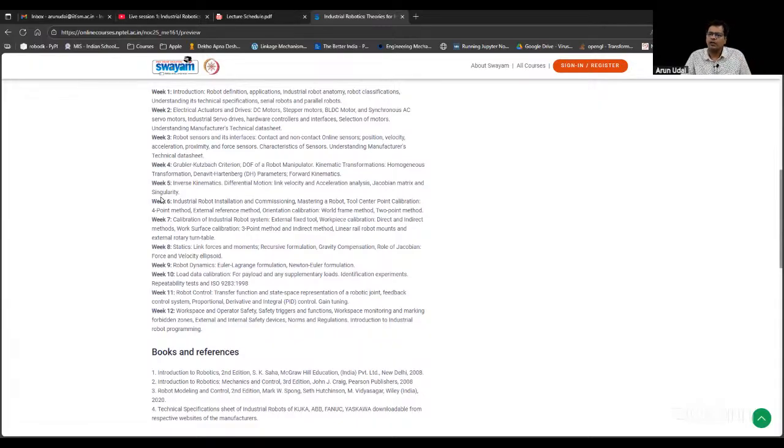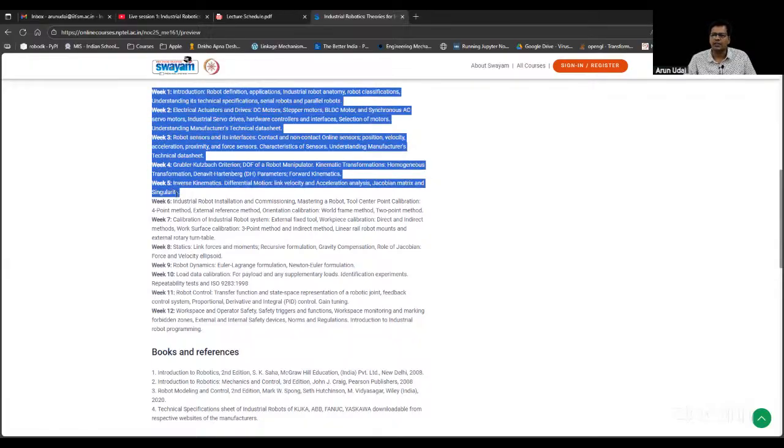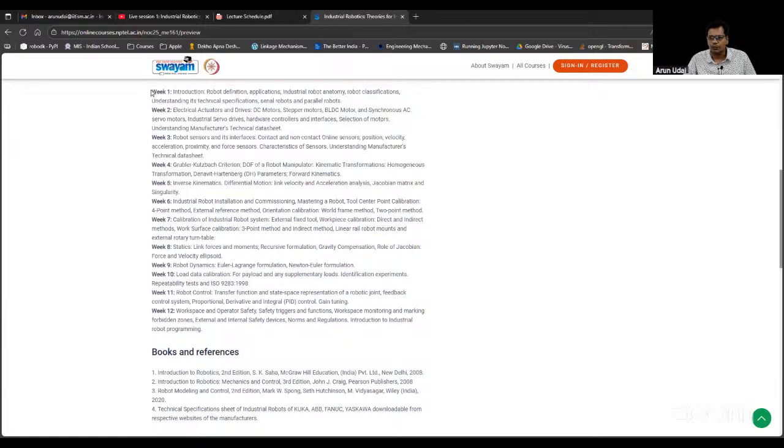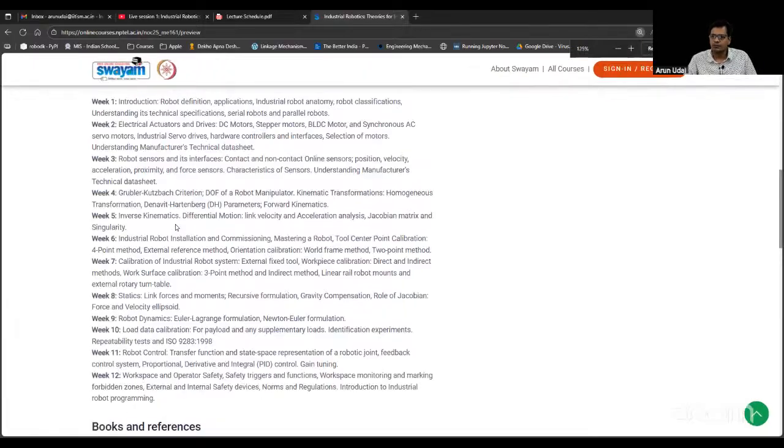So I covered almost a 6 degrees of freedom robot in detail, starting from 2 DOF, 3 DOF, 4 DOF, 5 DOF and 6 DOF. That is done. So you have almost covered the foundation of industrial robots. Most industrial robots work up to here like this only. They work with forward kinematics. That is very important. You should know it. You should know the DH parameters. If somebody wants to tweak the machine data file at times, you can do that also and still your robot will work. So that is the takeaway of this course, which I assume.